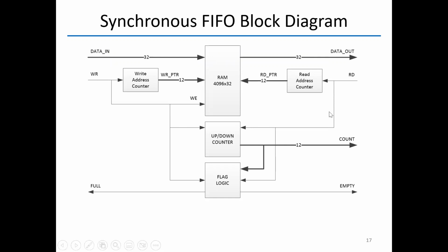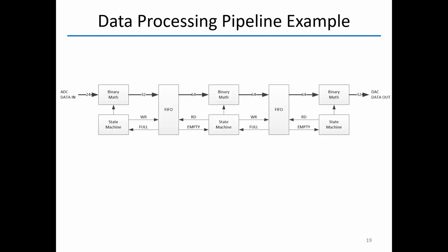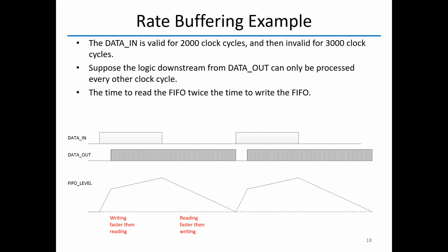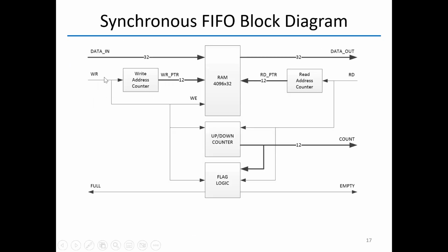And this is the write. And it takes a read from here, read command. So here I have a write command. The state machine has the built-in counter. It has the pointer. It has the flags to send. So all what I do here is write. Tell the first in, first out, I need to write. This is the one similar to this.